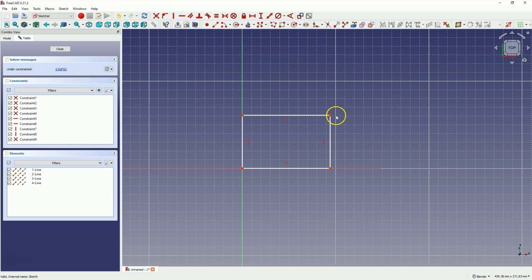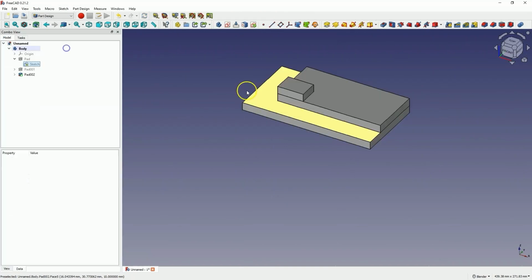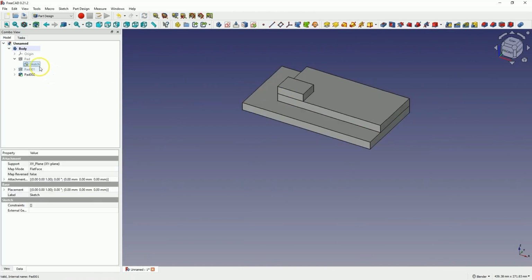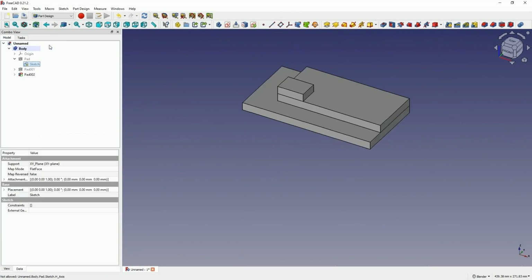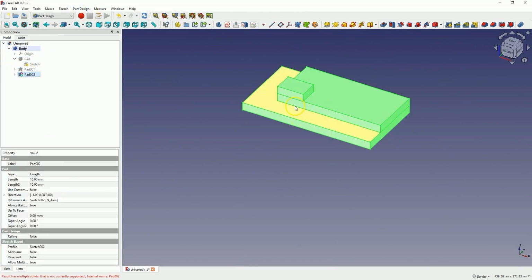If we only changed the dimensions of the sketch, did not delete any geometry or add anything, everything worked, nothing happened here. But if we change the shape of the geometry, for example, if I create something like this and trim parts of the geometry, then we already have errors here. The changes are not reflected in the model. Here, there is simply a warning that something is wrong.